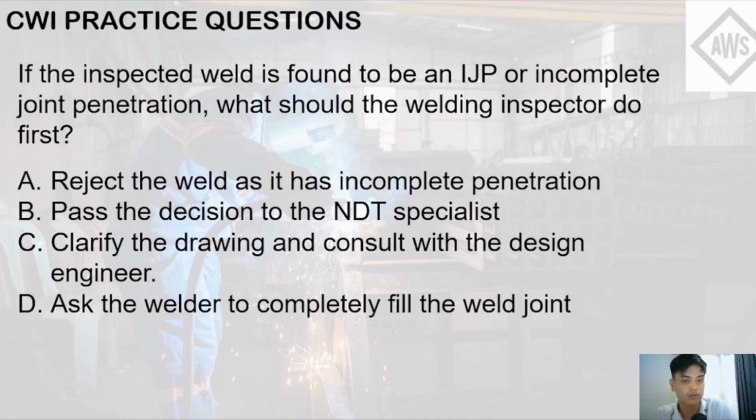So not quite. Basically, the choice here is vague. You may not need to pass the decision to an NDT specialist here. It needs not be specific to a non-destructive testing specialist. So it's just incomplete joint penetration. Basically, you can see the discontinuity or the defect just by looking at it. So the NDT specialist might not be the one that needs to be consulted immediately.